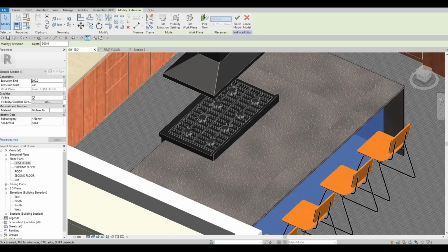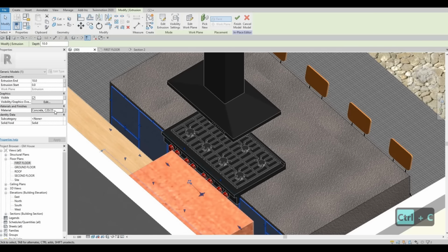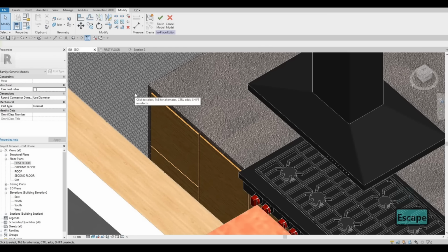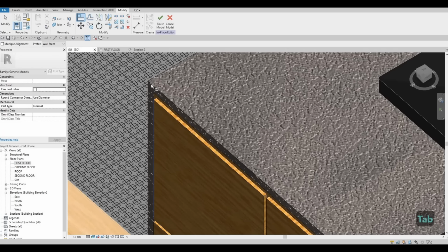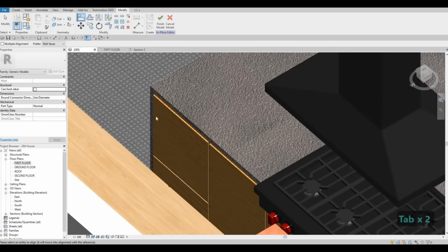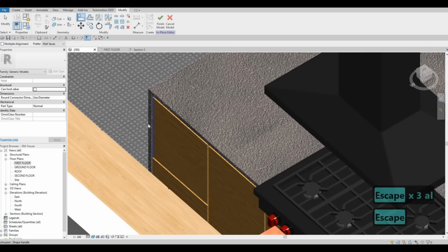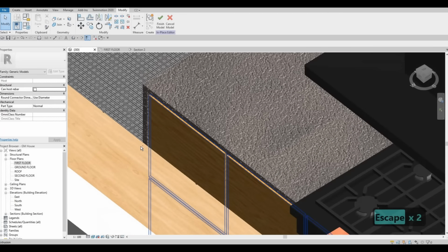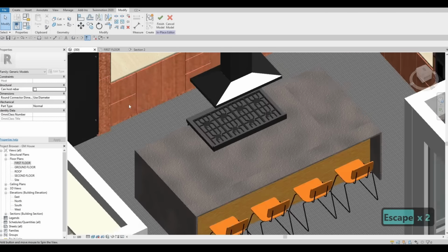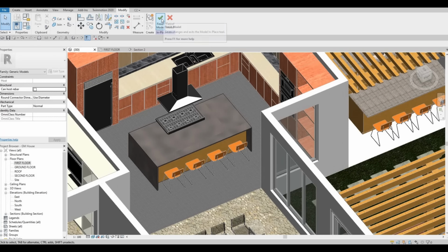So it should be Glulam 32C, Glulam actually. And then here we just need to click apply, and then it got fixed. AL, so we're gonna align the face so that everything is flush onto this side. So I'm just looking for this one to be highlighted, so the face. So now that looks good. So everything is added there. So now we need to click finish.